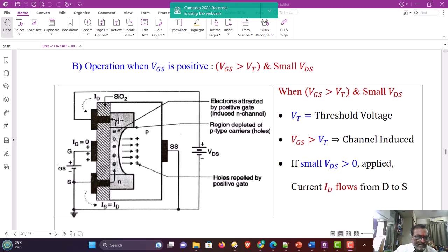Now we will see between drain and source terminals, there is a connection of a charge carrier channel. Now if we apply drain to source voltage, a positive supply connected to the drain terminal with respect to source, these electrons are attracted by the supply electric field towards the positive plate and they drain off from the drain terminal. Electrons are coming out and therefore electron current is flowing out. Therefore conventional current, shown here by the dotted line, is going inside.